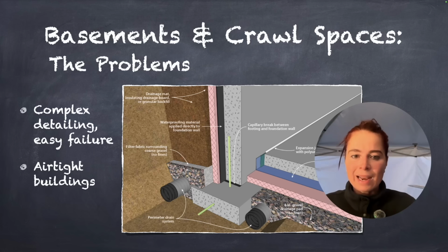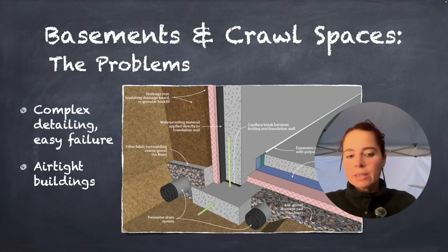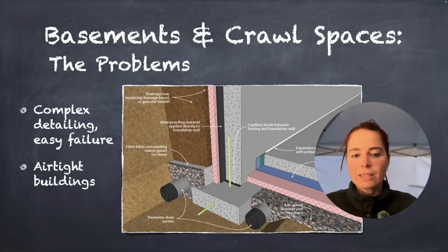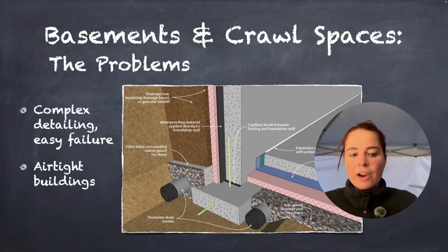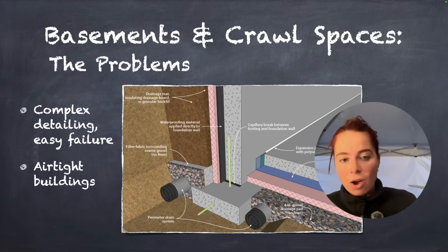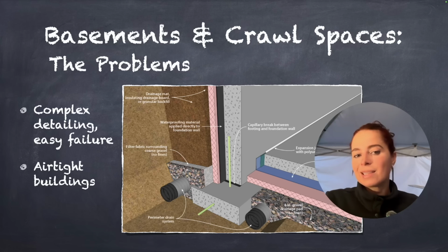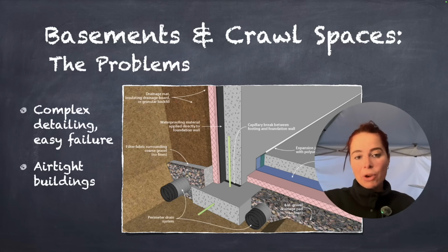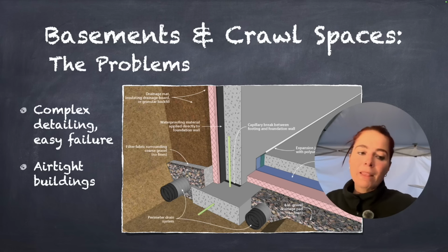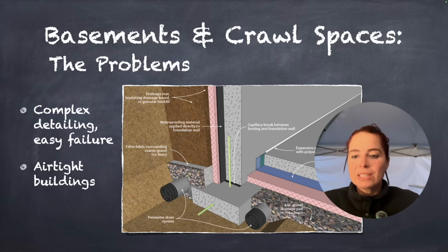Once moisture does get in, it's often trapped, and with modern finishes such as drywall, insulation, and carpet, it can create the ideal conditions for mold to grow. And then add to that, modern structures are really airtight. We're trying for energy efficiency, and I understand that's a good aim to have. But that also means that any toxic things that get in, be that soil gases or microbial growth, can't get out. And that really amplifies health risks within the entire house.